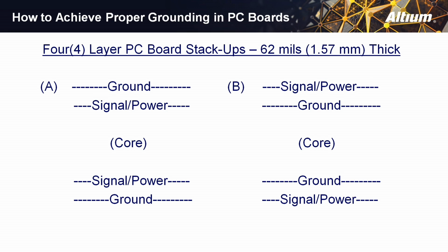The end result is that we actually got a lower impedance power delivery structure with this 4-layer board than we did with the conventional 4-layer board having power and ground on 2 and 3. Reason? We had higher capacitance in the power bus and lower inductance.